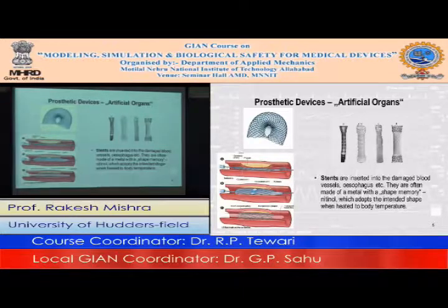Now in this particular case, the design of a stent is a unique feature. For example, it's a mesh. Typically, we don't want metal inside the body, and the upper limit is 15%. We should not have in a given area more than 15% of the material coming from the metal, or now lots of composites and other things. Now, what should be the structure of the stent? It should be closed like a circle, or it should be open, an open circle, not a completed circle.